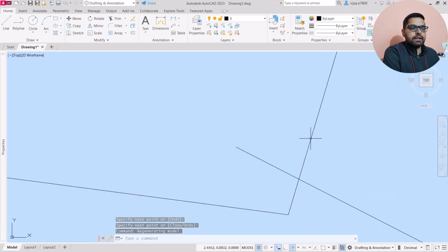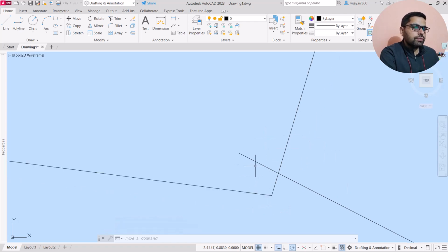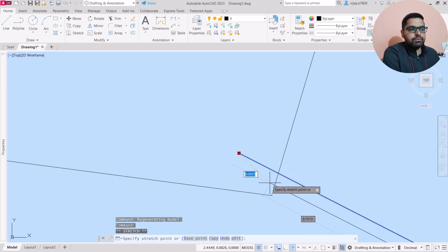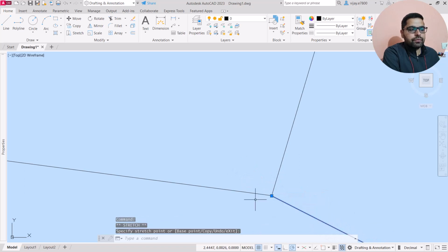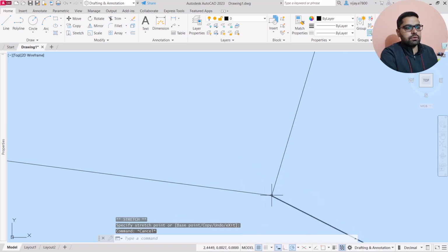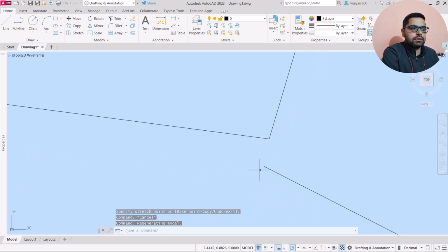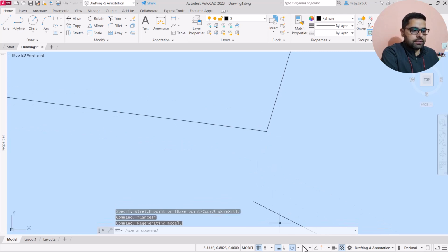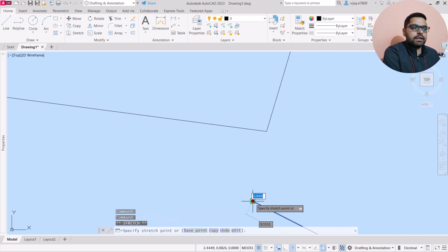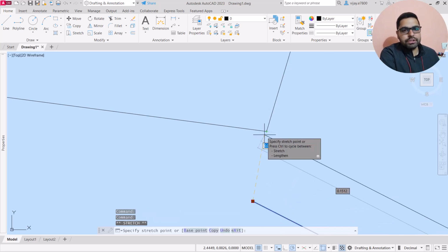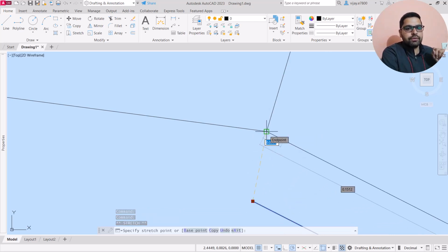Take a look at the line that you have started. From the zoom level, we thought that we were starting the line from the exact corner, but this was not the case. Now I'm taking this corner and I'm again placing it at this edge. Now just take a look. I'm going to zoom in further and you will see that again we have not joined the line at the exact corner. So Osnap is basically a criterion that allows us to join at certain points effortlessly.